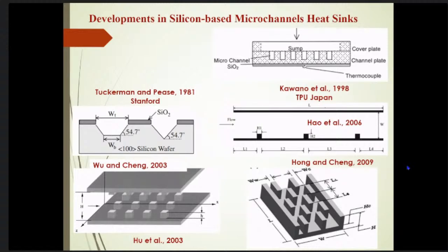So we need to control two things: we want to maximize the heat transfer, as well as keep control on the pressure drop and the pumping power. Because when we do it at the micro scale, we have to keep an eye on the current state-of-the-art micro scale pumps that can be integrated with this system, what pressure and flow rate these pumps are producing.